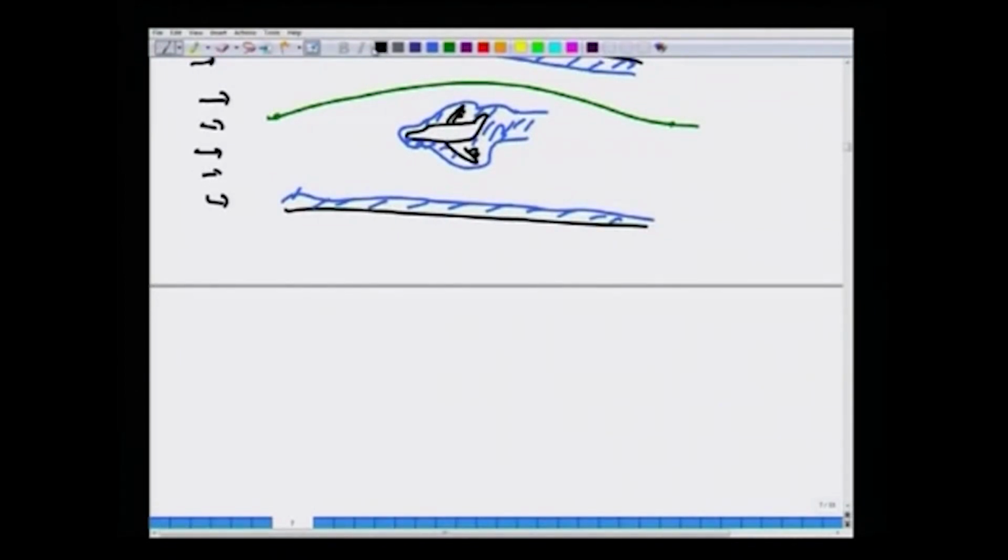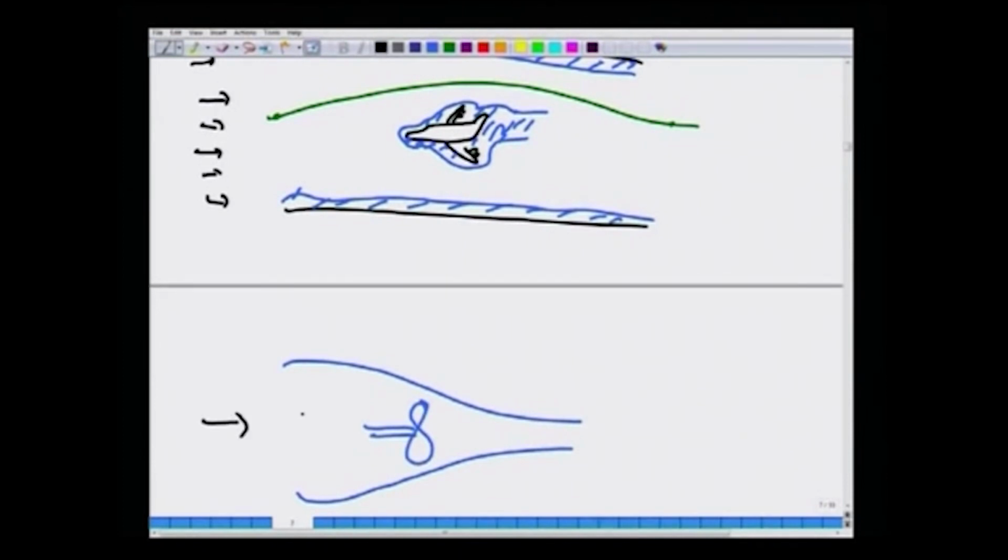Likewise, let us consider another context, okay. You may have a conduit like this, and you may have a fan or a blower, and fluid is coming in like this and going out like this, okay. Close to these solid surfaces, viscous losses will be important. So, you can apply the Bernoulli equation upstream and downstream of this blower or fan, along a streamline, but you cannot take the streamline across this fan, because viscous losses become important. So, the Bernoulli equation is valid, okay.